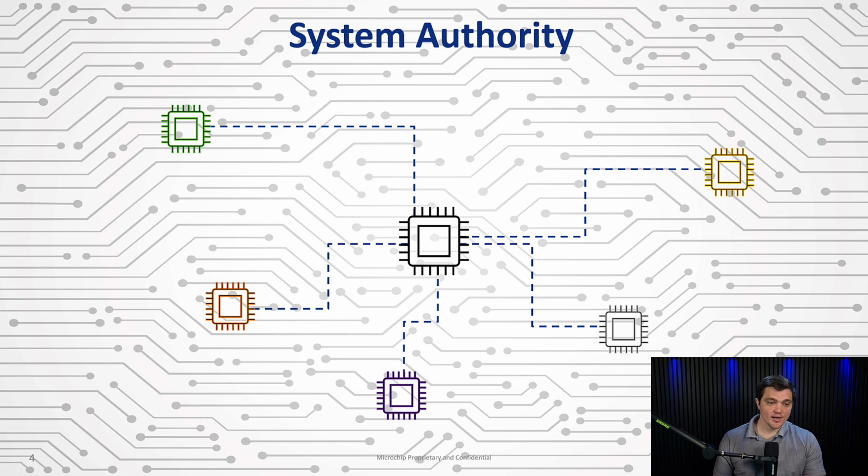Now, what this might look like in practice is you will have maybe the application processor, maybe some other device that's meant to be the attestation requester. And what that will do is send out a request to a device for it to attest itself. And what the CEC1736 does is it will generate its private key, as we explained, from its SRAM PUF, and it will then use that private key to sign the response to the attestation requester, and then sends it back. If this signature is considered valid, we will then have passed the attestation request and it will be allowed to operate as intended.